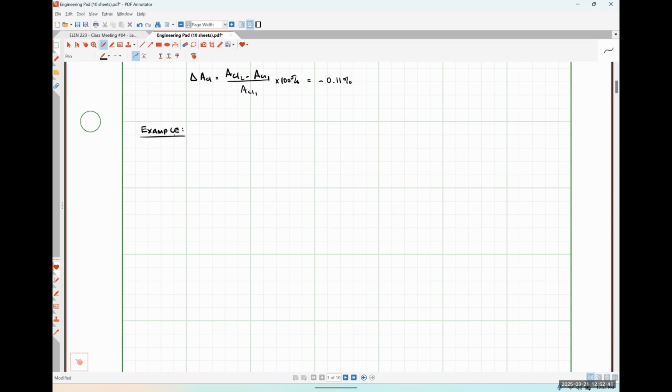So this is the circuit that I want us to analyze. I've got my op amp here. I'm choosing to put my inverting input terminal on top. Here's VCC plus and VCC minus. I'm going to give myself negative feedback by connecting some resistor between my inverting input node and my output node.